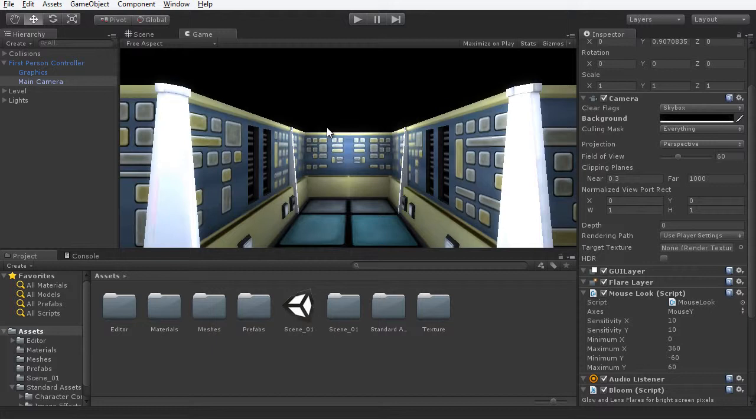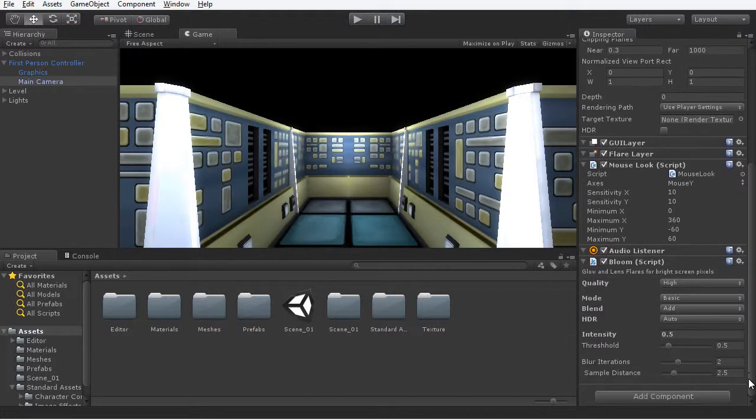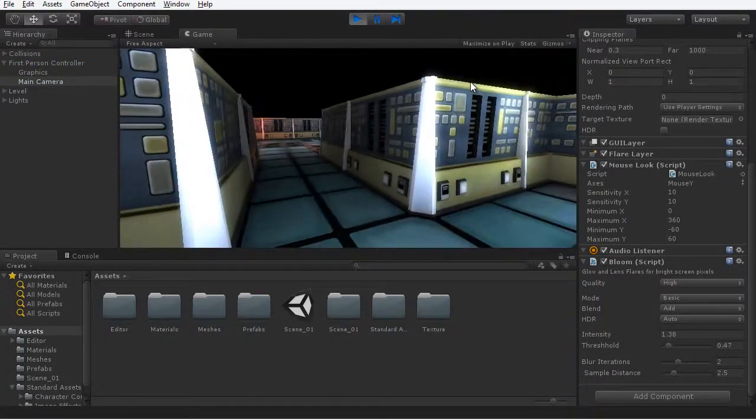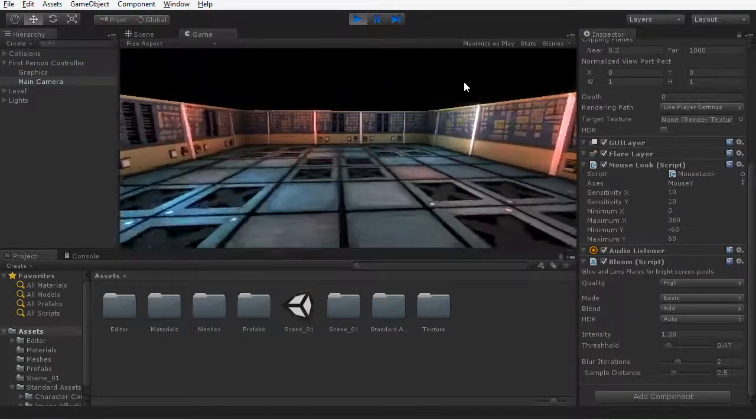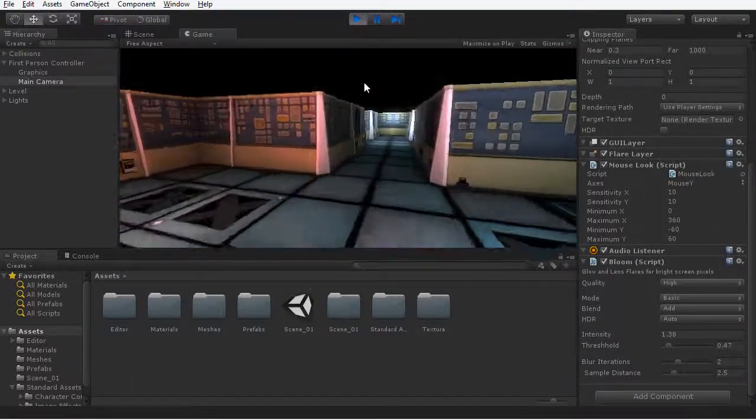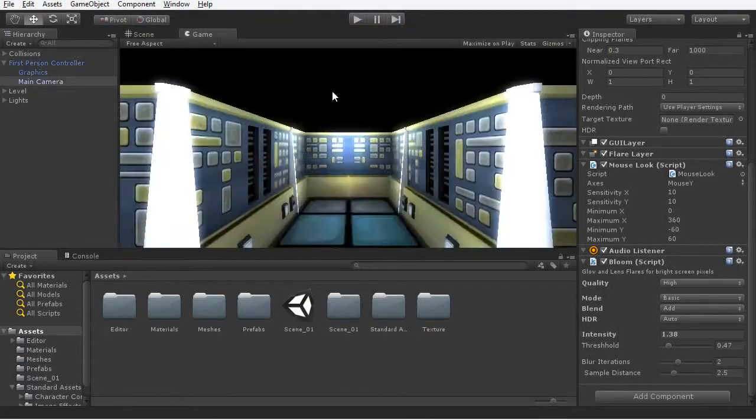and I'm going to be adding a bloom effect here. So again, right now I've added the bloom effect, and I'll scroll down so we can see the properties for that. Let's just increase the intensity, and already in the viewport as I do that, make sure you're on the game tab, you can see this taking effect. And maybe decrease the threshold just a little bit. Now if I press play on the toolbar, let's just see the effect that the bloom takes on there. So I think that gives us a nice blur around the highlights of the level. So I'm going to accept that, and then I'm going to add the fisheye effect.